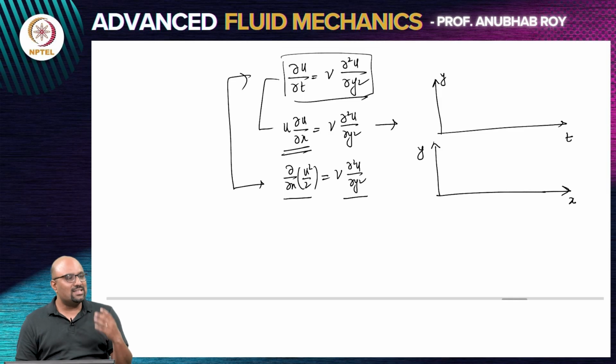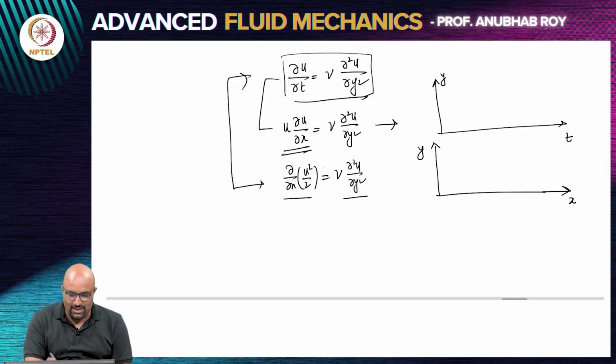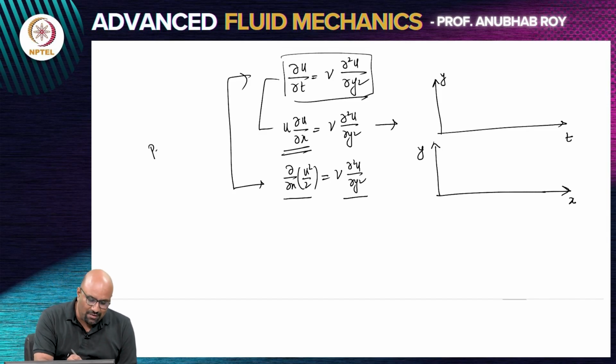You can already start anticipating that the flow coordinate x is going to have some correspondence to the temporal coordinate. There is some kind of an initial value problem where the initial condition is not at t equals 0, but at x equals some x naught. So you are going to march. These are basically known as equations which have parabolic character or parabolic nature.